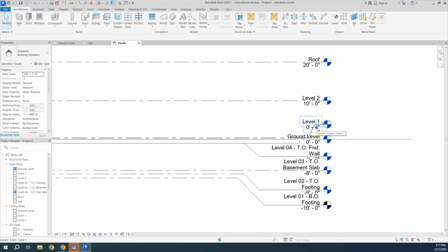So I am setting my level 1 to 4 inches because I want my building to start there. This allows me to build a 4-inch tall sidewalk around the outside edge of my building. But that means when I start building my building, it's going to be floating. So you are going to have to make some adjustments. You're going to have a foundation wall that's going to go from your lower level up to level 1. So that will actually make it so it isn't floating later on in your project. But for the moment, it's going to be floating 4 inches above the ground.